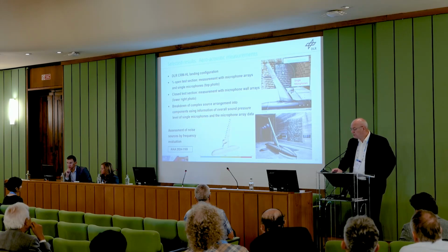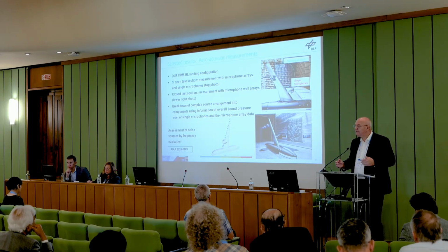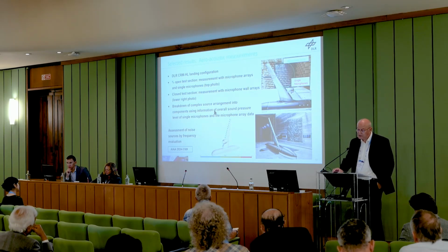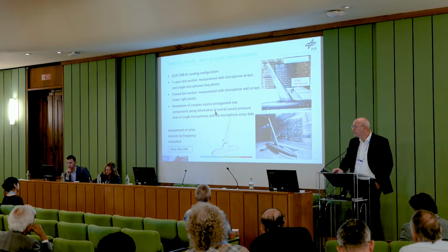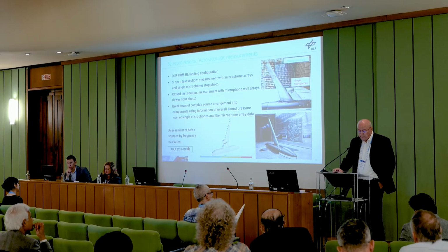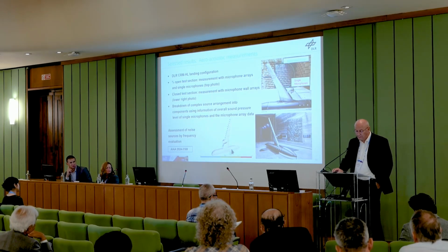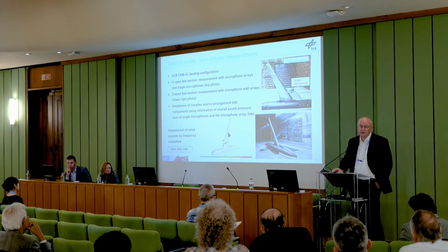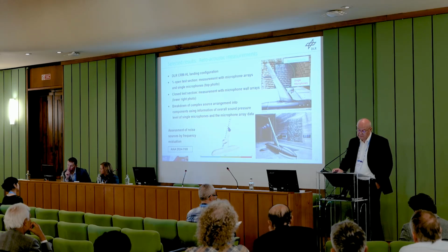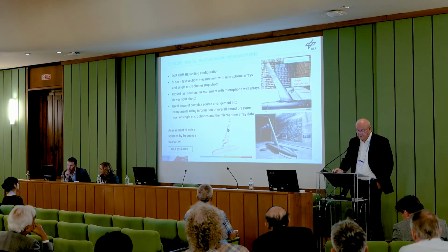In the open test section we also had single microphones, in order to combine these measurements and get not only source information but also sound pressure level information by doing the appropriate evaluations. This is all ongoing work. A paper is out for the acoustic measurements in the closed test section, and here's an example. It's a frequency plot, a source localization, and you clearly see the large impact of the slat tracks for this configuration, which is really expected.